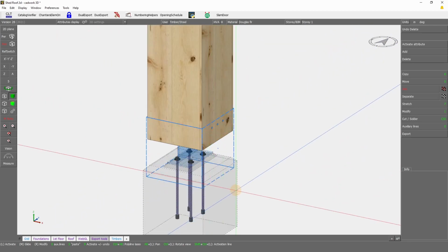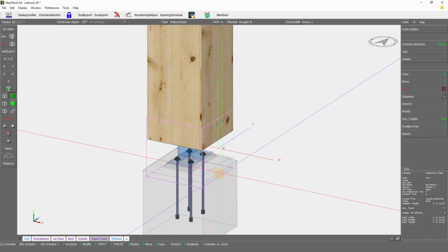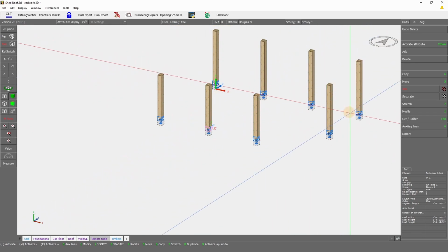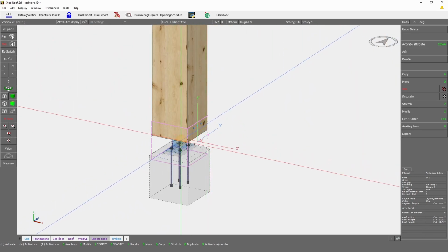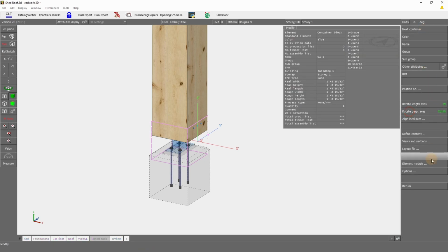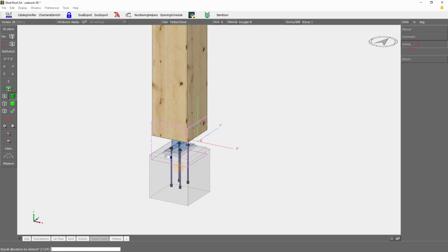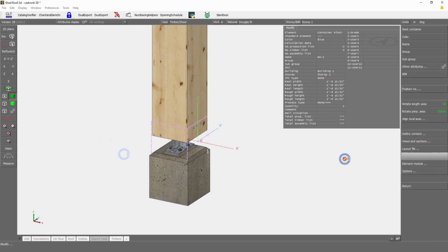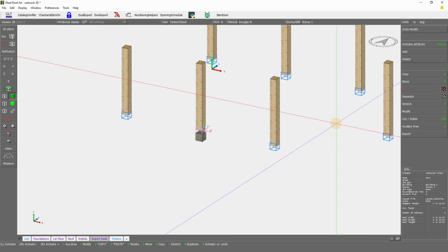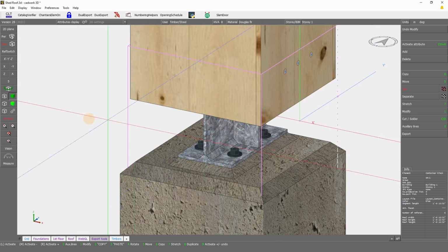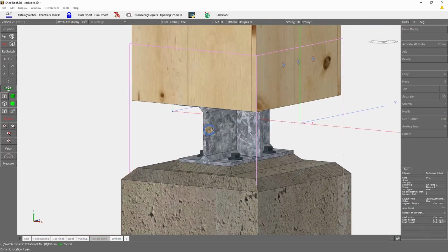So if I want to edit what is assigned to a container block, what we need to do is change the content, because this is what we see in dashed lines. What is assigned to the container block is the content. So if the container block doesn't have any content, then we are free to modify anything we need. So Modify, Define Content, and here just delete. By deleting the content, of course, all the other ones will be emptied. So here we can do any modification we need.